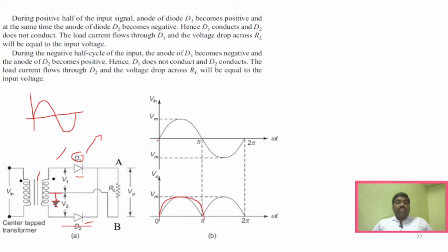So it allows this particular voltage to flow through. Conduction will take place. Whereas in the reverse direction, that is in the negative cycle, this becomes negative, it will be turned off, and this becomes positive, right? So conduction will take place, but now in the negative half cycle, and it will also provide the same waveform.